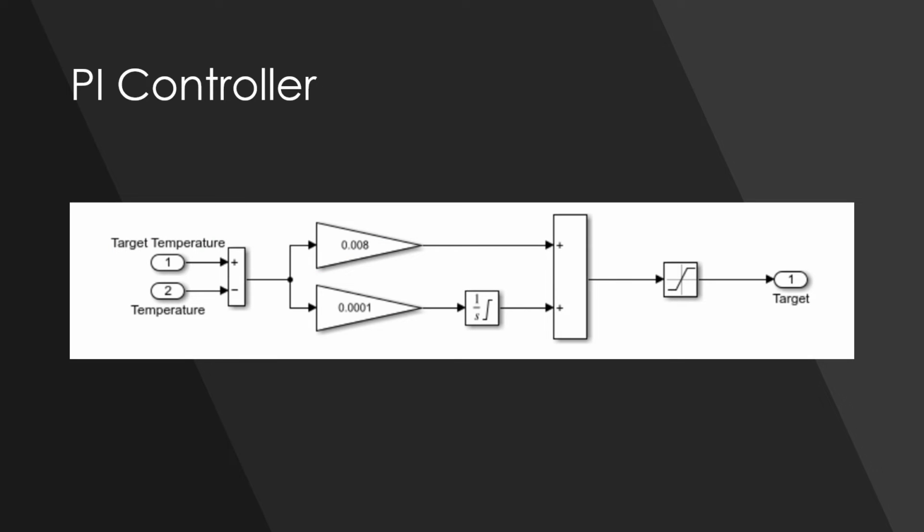If we take a closer look at the controller from this example, this is actually a PI controller, and it's commonly used in industry. We don't really need derivative, as we're not super worried about abrupt changes or noisy signals with the temperature from a house, so the derivative is not super necessary. And you can see here there's the input temperature and the error temperature from the thermostat.